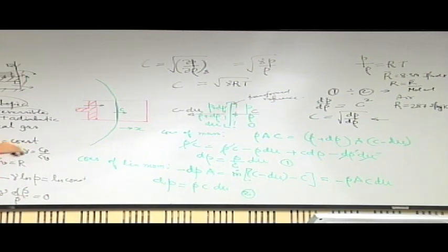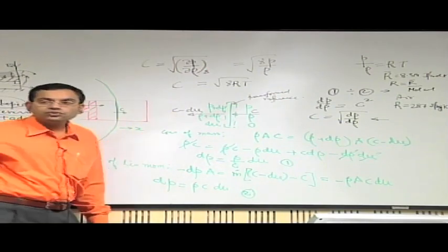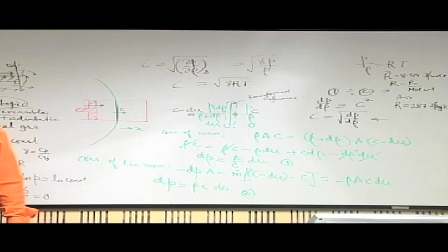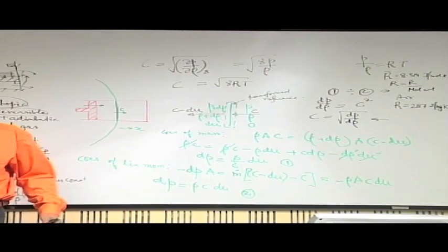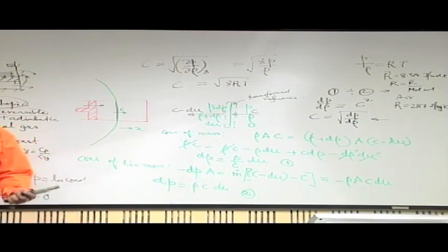So for a normal temperature condition, this will be close to 340 meter per second, and since sound wave also propagates in the form of a weak pressure wave within a medium, it is a natural coincidence that this is also the same as the speed of sound in a medium. Sonic speed is not the speed of sound in a medium by fundamental definition, but because sound also propagates in the form of a weak pressure wave, it is scientifically coincidental that they are the same.